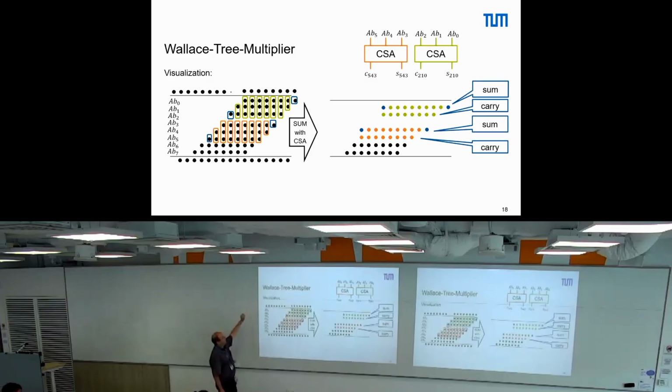I first want to explain what the indexes I have here in the slide actually mean. B0 till B7, we could also extend this to further bits. This is just the bit value of the multiplier. So A is the multiplicand. The left side is A, the right side is B, and we do this bitwise because we want to compute this AND. The first line effectively is B0, so this bit ANDed with this one here.